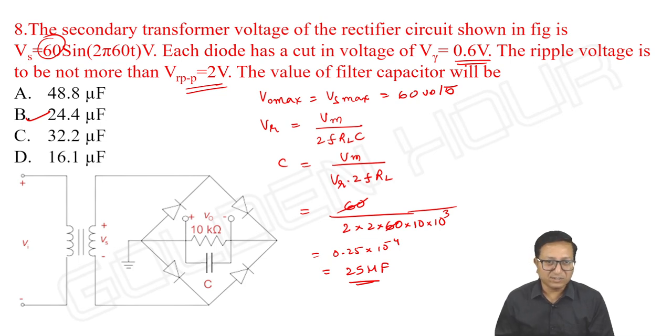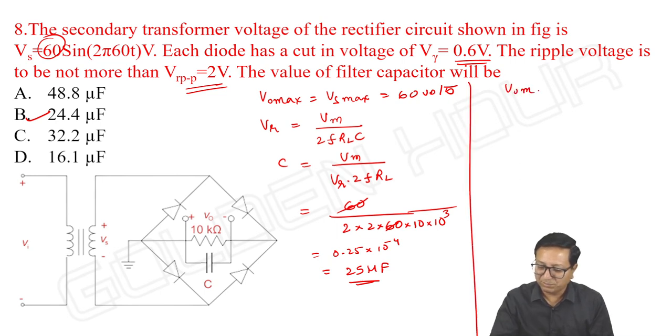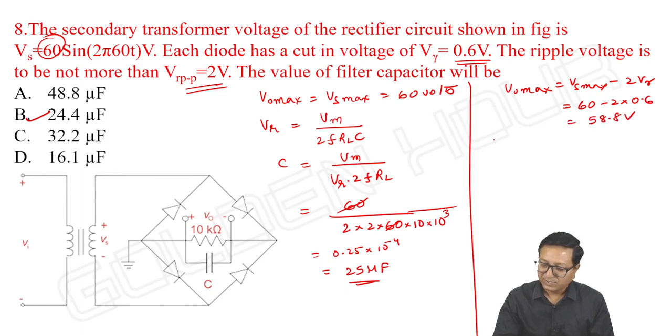Alternatively, what do we do? Definitely V output maximum is equal to 60 minus 1.2. It is a bridge type rectifier now. So alternatively, we can write V output maximum is equal to Vs maximum minus 2 into V gamma. It is 60 minus 2 into 0.6, which is 58.8 volts, and Vr is equal to...